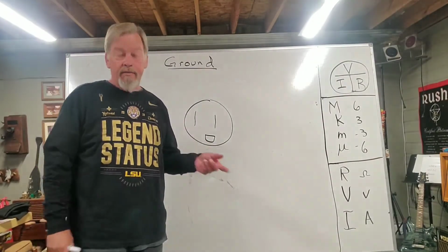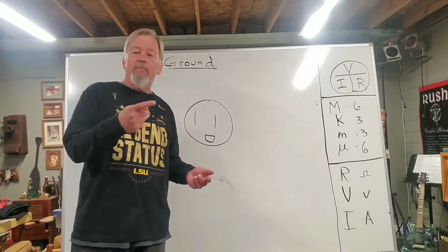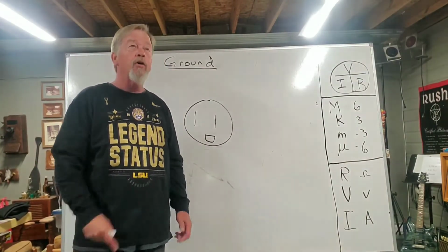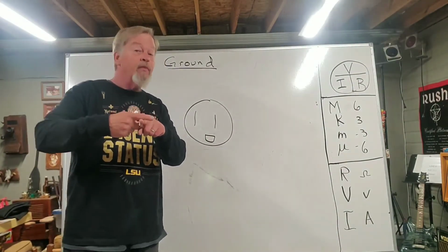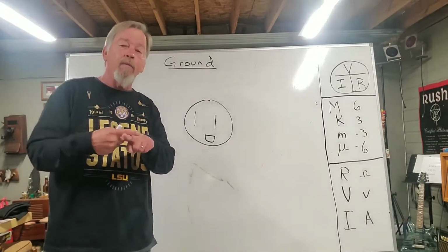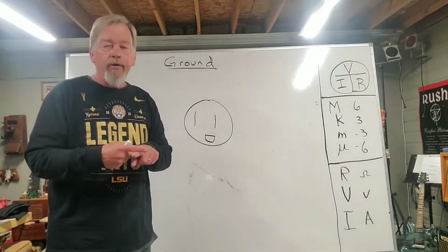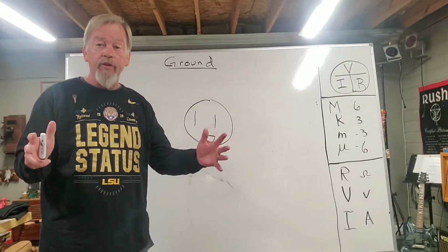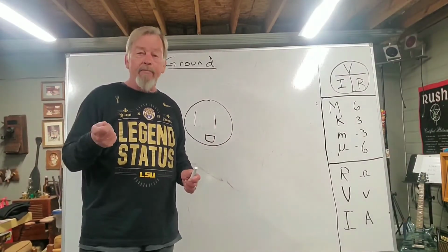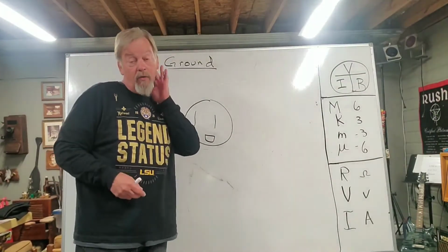And as I came to realize later on in life, what had happened was, because of the vibration of the compressor and the motor, the power cord was rubbing up against the metal frame. It eventually wore down until it had bare wire up against the frame of that refrigerator. So that put 120 volts on the metal outside of that refrigerator. Anytime you walked up to it, it was just like taking a butter knife and sticking it into a receptacle. Lord have mercy, it would light you up.